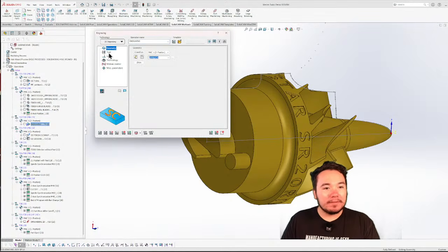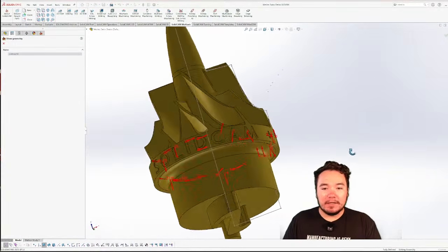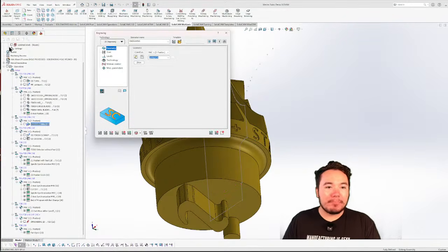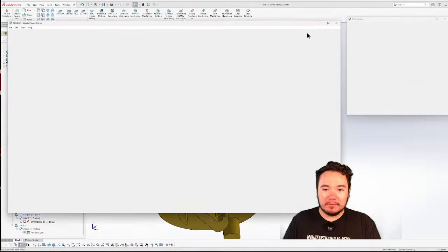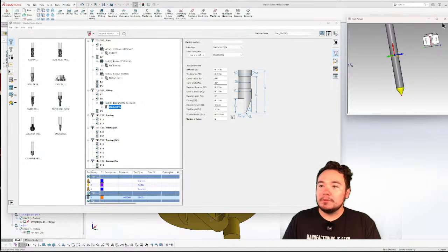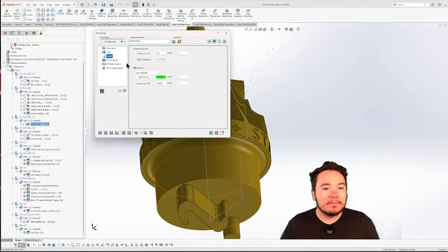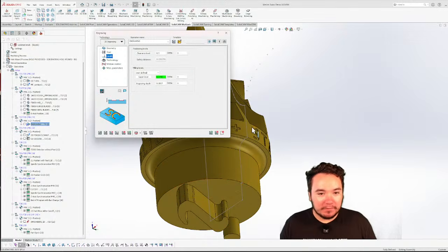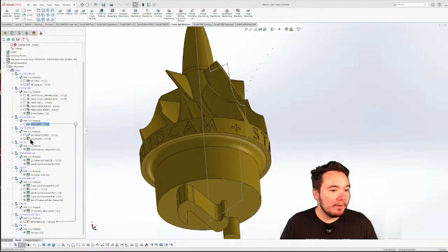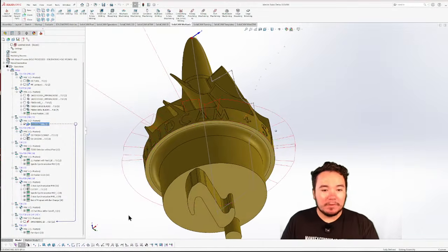Okay, so since we got the engraving, I just selected all the text here. I did that just by faces. Went and grabbed my tool, just an engraving tool. Selected it. Chose my upper level, the OD of the part, and my depth for engraving, 6 thou, 7/10, almost 7 thou. Seemed to turn out pretty good on the part. You can see that toolpath there. Pretty basic toolpath.